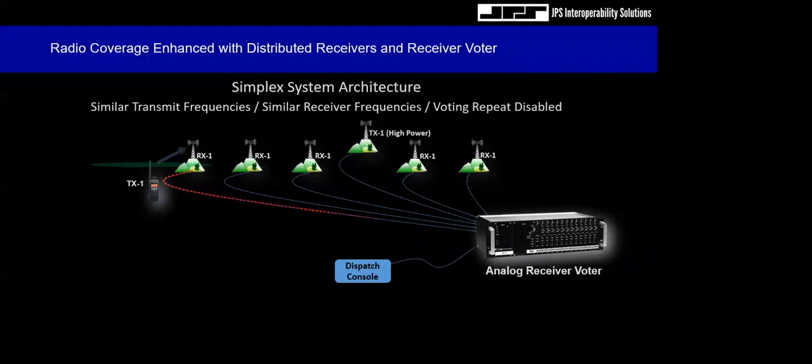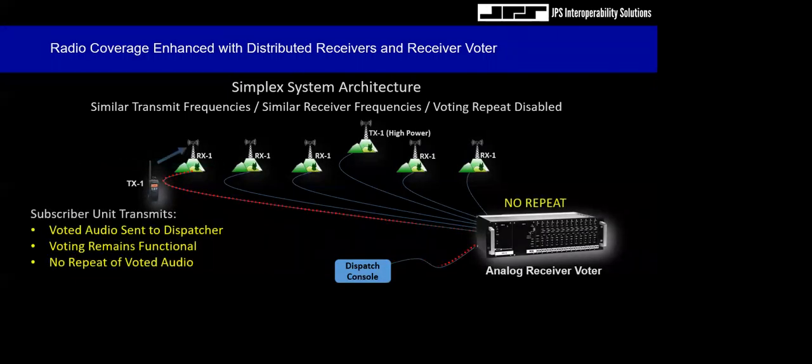So one of the last systems I want to talk about is a Simplex system. Remember, our first discussion was talking about unsupported or non-supported Simplex, where we don't use infrastructure. We just talk handheld radio to handheld radio, car to car, because we transmit at the same frequency. There are Simplex systems that use receiver sites, and they're primarily used by fire protection districts that have an area of responsibility that might be a national forest, BLM land, where they need radio coverage, where they can send communications back to a dispatch center.